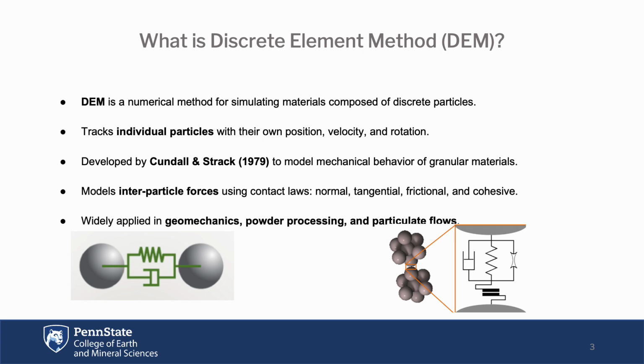The discrete element method, or DEM, is a numerical approach that models systems made up of discrete particles. It was first developed by Cundall and Strack in 1979 for rock mechanics simulations. In DEM, each particle is treated as an independent body with its own position, velocity, and rotation. These particles interact with their neighbors through contact forces, which are calculated explicitly using physical laws.